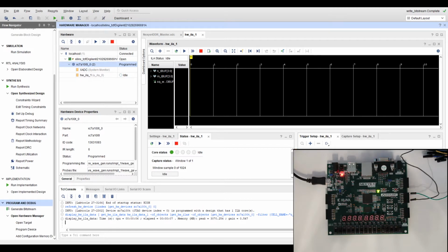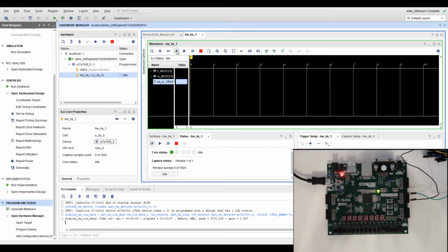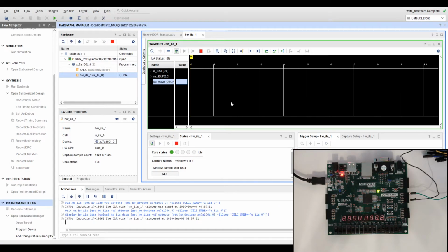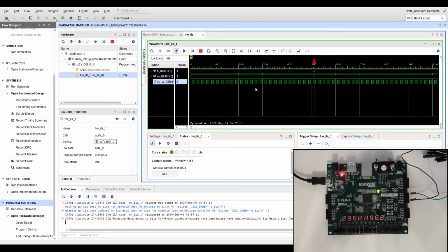the simulation window, or it's not the simulation, it's actually the ILA, the integrated logic analyzer window. So I do have the N buffer, the M buffer, and the square wave, and I'll be able to see everything in here. So you're going to have to click this one here. It's a little bit on the slower side, that's okay. All right, you're going to click on that, and then for example, if you wanted to run continuously, you run that, but if you just wanted to capture just one with one trigger, you're going to click on here, and what you're going to see, you'll wait a few seconds, and you get this window.